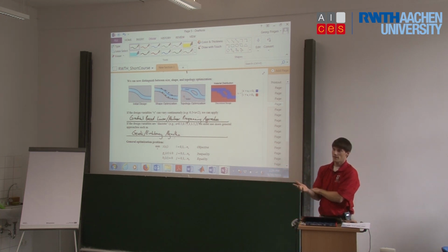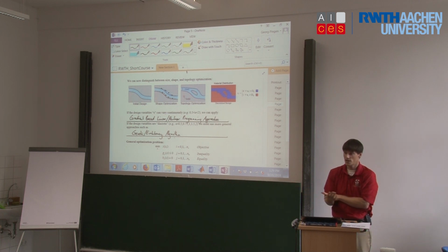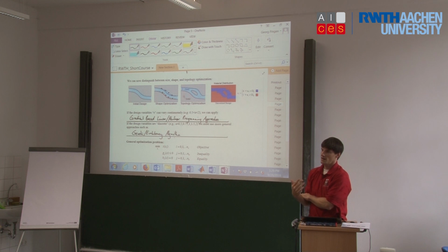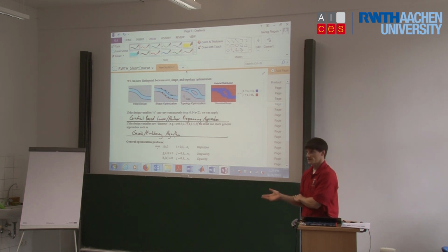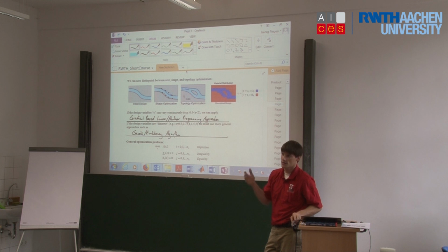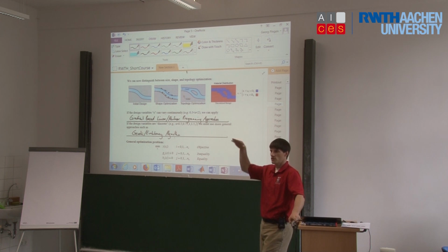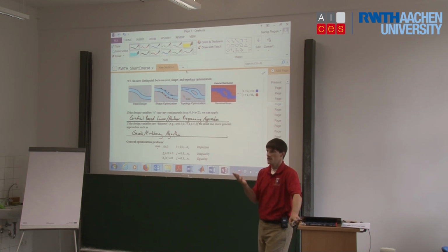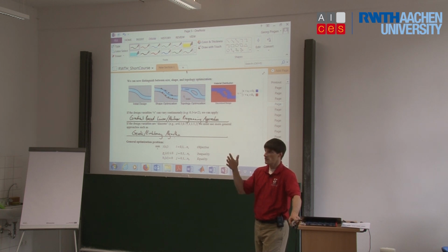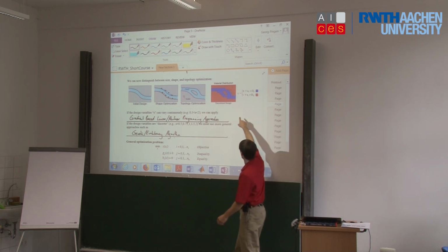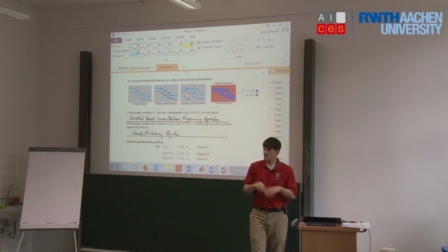I don't have much experience with genetic or evolutionary algorithms, but if you're looking at industry applications of design optimization with fluid dynamics, they often use evolutionary algorithms, and they're very effective if you only have a few design variables. You can apply an evolutionary algorithm to improve the shape of an airplane wing if you define maybe 3 or 4 parameters that govern the shape. In that case, it's computationally feasible. If you use a topology optimization problem, this mesh would be way too coarse to represent an airplane.